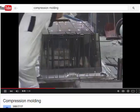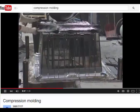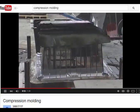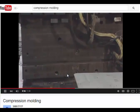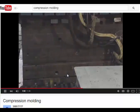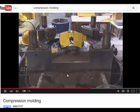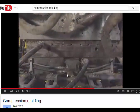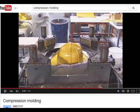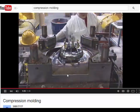The compression molding process typically involves placing a pre-cut, pre-weighed charge of material onto the lower half of a heated mold. The heated upper half of the mold is then lowered rapidly, causing the charge to flow, compressing it to the required density and shape as defined by the mold. With some presses, the lower half of the mold moves upwards, forcing the mold halves together. Once the material cures under the heat and pressure, the press opens, and the compression molded part is demolded, typically with the assistance of an ejector system.